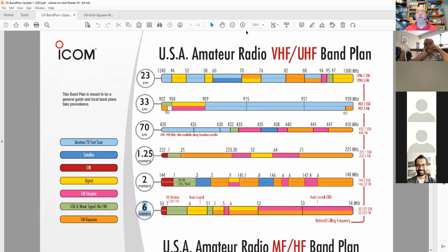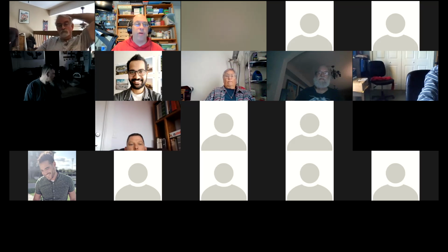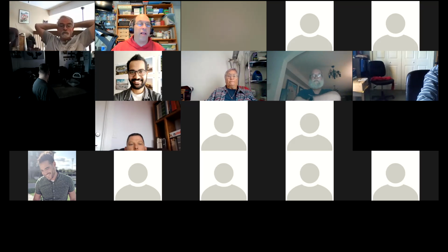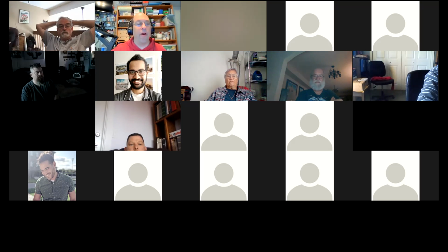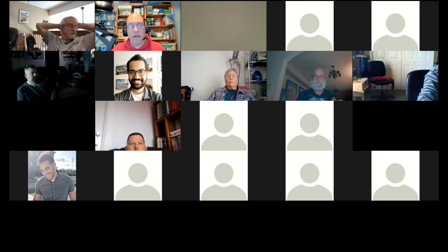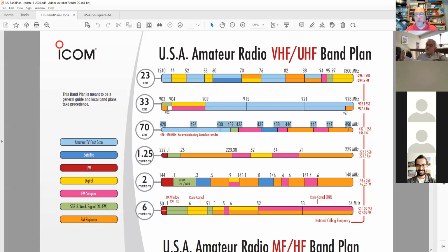In addition to that, you might also find that you hear other stations on a band where you think you are allowed to be. They are possibly allowed to be there too, because they might actually be primary or secondary users. We're not always primary. On that 70 centimeter band, that big swath from 420 to 450, we are actually secondary users to the US military.